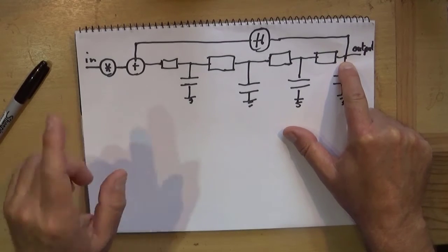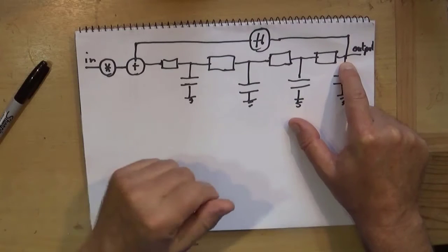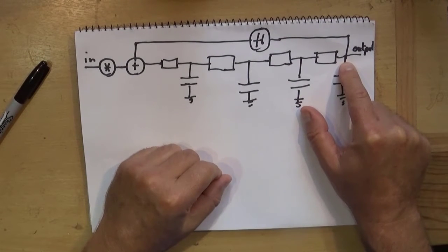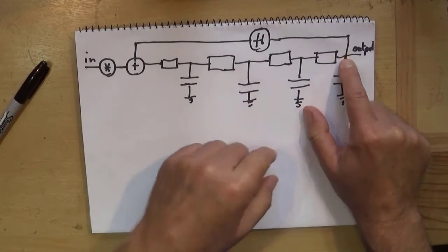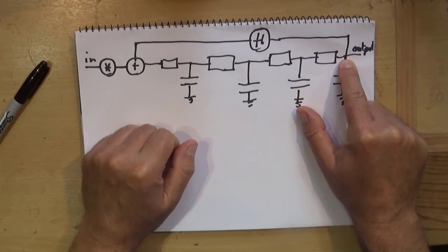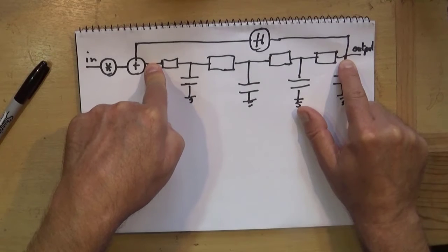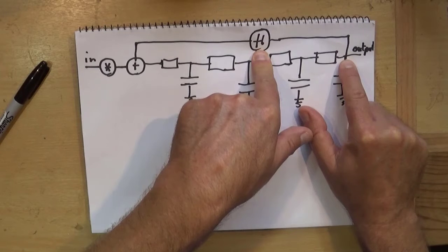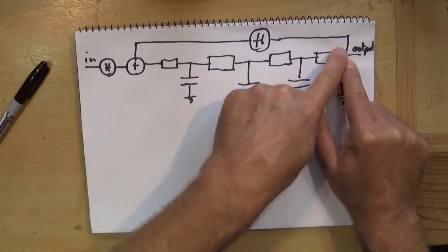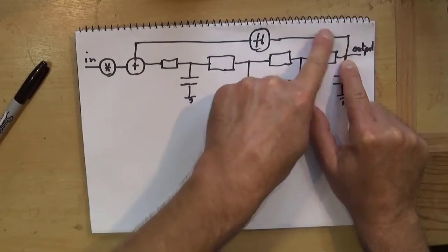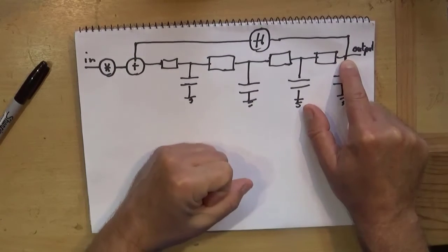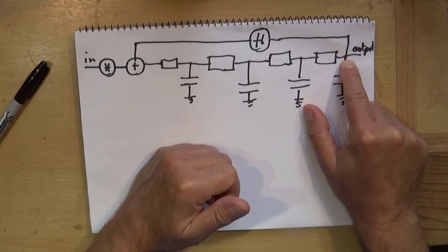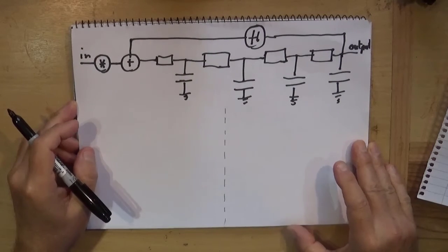this point, if say we're putting a sine wave in, we're characterising the filter, we're always considering sine waves. We're putting a sine wave in. This point is 180 degrees phase difference to this point, or out of phase. So if the feedback is negative, then that will reinforce this, and we will get actually an amplification at that frequency.